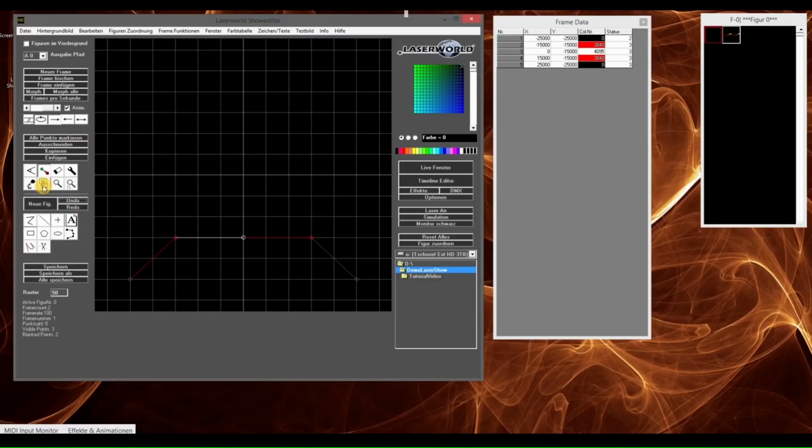Okay, you maybe have recognized that we accidentally deleted the second frame when doing the undo for a mistake. So we just need to redo the procedure for the middle frame. We just redo it, just move it back to the initial position. Then we do a copy, right click, we mark all points, Control A, move them,